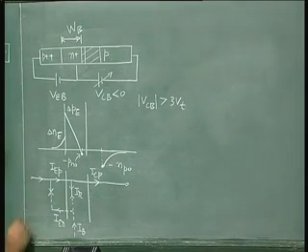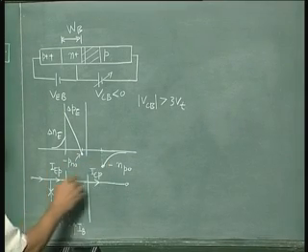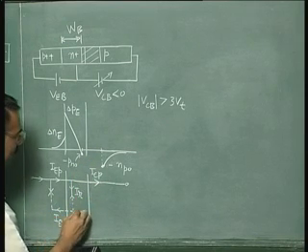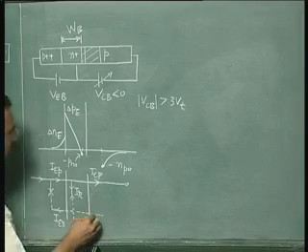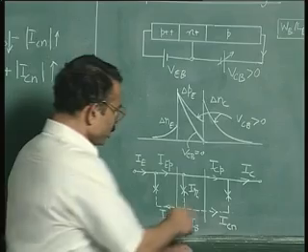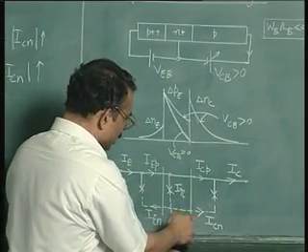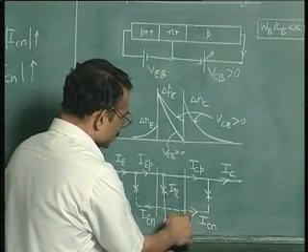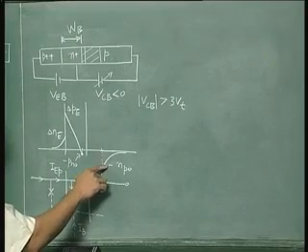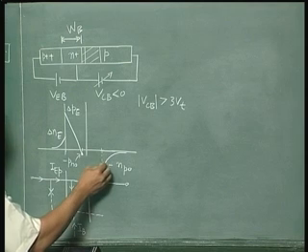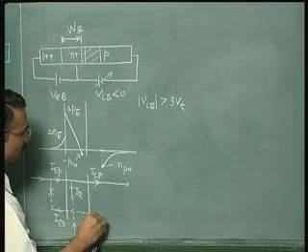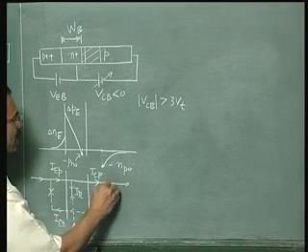So what is the result of this? The result of this is, now this means that there is a small current here, ICN, but it is in the opposite direction to what it was when there was a forward bias. So forward bias, the electron current was injected from base to collector, but for reverse bias it is the other way around. This is clearly evident from this slope. This slope indicates that you have flow of electrons like this. So this is really a generation current,